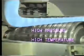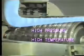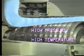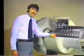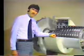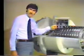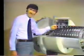Now, with an increase in pressure goes a similar increase in temperature. So the air leaving the compressor has gained high pressure and a high temperature. This is done by alternately speeding up and slowing down the air in an ever-decreasing volume of air path. The question you may be asking yourself is, how does air movement get changed into pressure? The answer is related to the shape of each compressor blade.